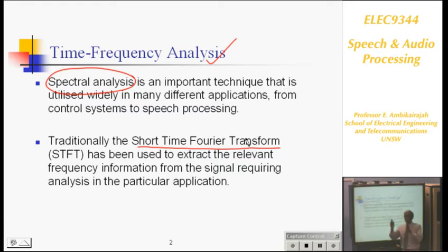Because the waveform is varying in time, you can only take a small window. That's why it's called short time Fourier transform. Using it, which you have done in the lab, we can extract the frequency information available in the signal.